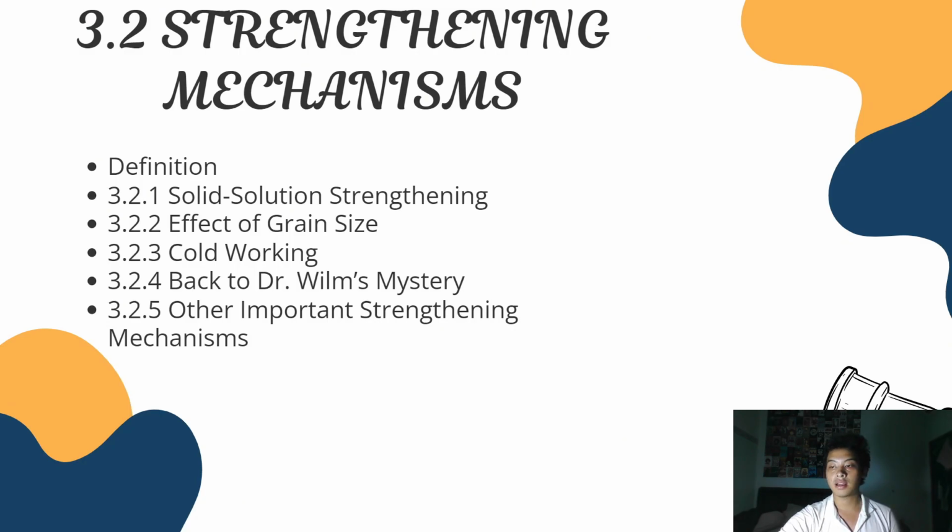Cold working. If a metal is deformed at room temperature or up to approximately 0.3 Tm, where Tm is the melting point on the absolute temperature scale, the microstructure becomes deformed due to cold working, also known as work hardening or strain hardening.